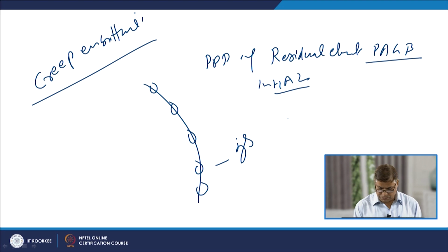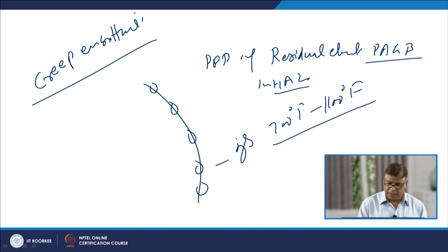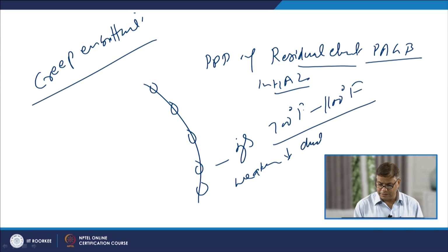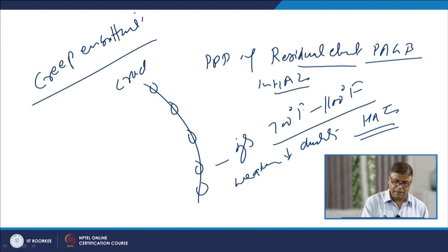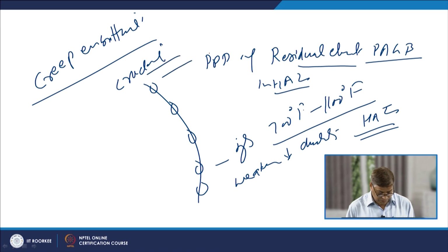like say this temperature is around 700 Fahrenheit to 1100 Fahrenheit. So, exposure in this temperature range leads to the precipitation of the residual elements at the prior austenite grain boundaries, and this precipitation weakens the material, lowers the ductility, and increases the embrittlement of the chromium molybdenum steels, especially in the heat affected zone. So, prolonged exposure leads to cracking in the heat affected zone due to the creep embrittlement,